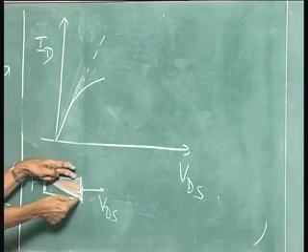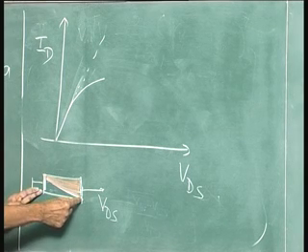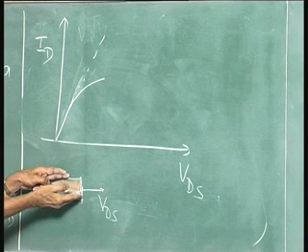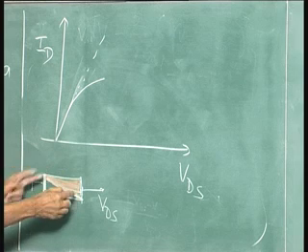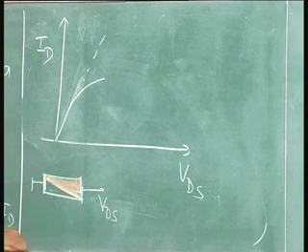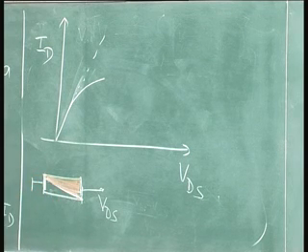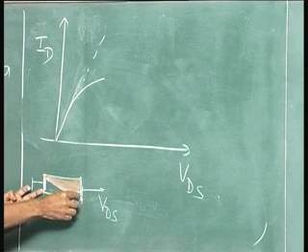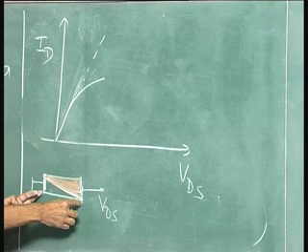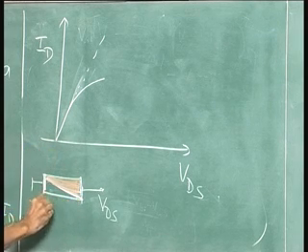Now, that is VP0, and this voltage cannot change beyond that point, because if it falls, the channel will open up, but it has reached an equilibrium situation where that is held constant now. So, this is just about to close. Please understand this very carefully: you have a situation here where this voltage now remains constant, such that this is VP0. So, what is this voltage now?